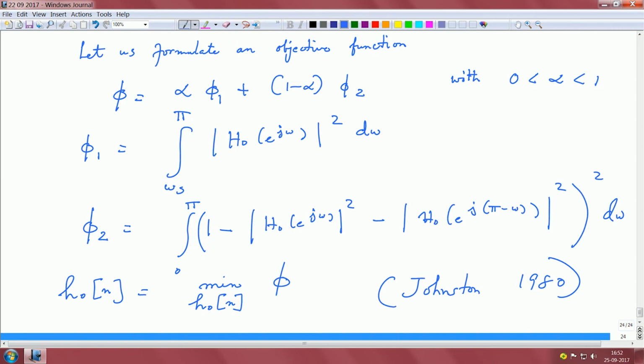Then to simplify your design, you assume the quadrature mirror property, so that given a base low pass filter you can construct the high pass filter as well. Then you analyze the magnitude distortion function, you analyze the distortion transfer function, and from that you simplify further to look into the phase distortion and amplitude distortion, and then construct filters that can minimize these distortions.